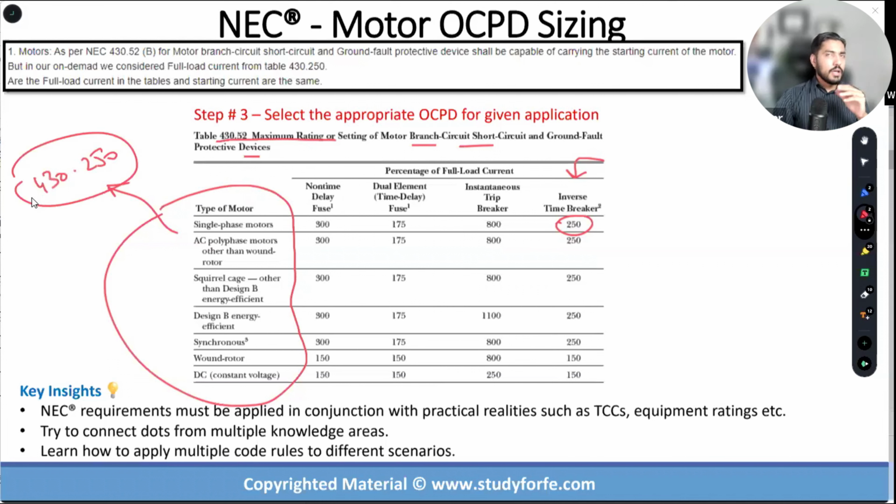There are other tables, like I think single phase motors are in a different table, 430.248, I believe, right? But for three phase, this is the go-to table. And most of the motors we encounter, the big motors, are all three phase. There are smaller single phase motors in small fans and this and that. But yeah, okay.